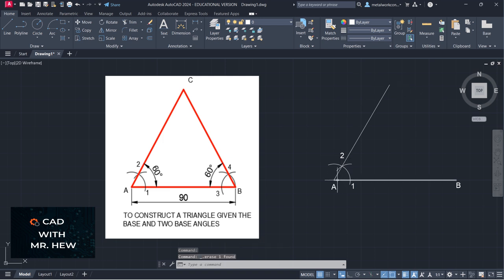Whenever I'm extending a long line, I use the extend command. If I'm just extending it, like when I bisect a line, if you look in the previous videos where I drew the bisector, I didn't do it like this. I just grip the end of the line and extend it to 2 or 3 or 4 millimeters. When I'm extending it longer than 20 millimeters, I like to use the extend command so that it is accurate.